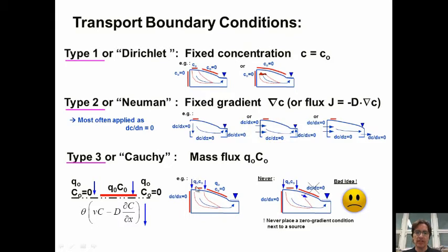So here's some context again. At a source zone, we can impose a third type boundary, and outside this source zone too, whether up gradient or along this boundary, can also be third type. If it's far enough away, it can be zero gradient, as in this case. The advantage of a third type here is that we're not imposing the concentration along the boundary. We're imposing it outside the boundary, but the actual concentrations along the boundary remain part of the solution. So it's a little freer condition. We're not imposing the concentration now. We're going to let it build up naturally with this dispersive term.